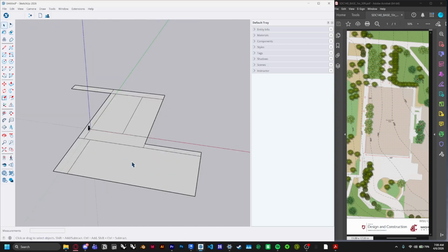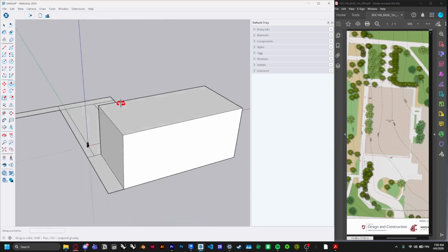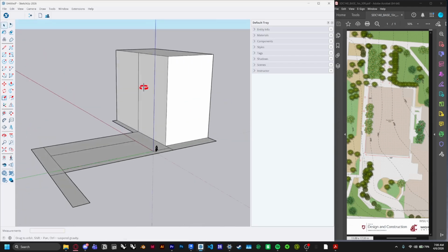Now that you have the Carpenter Hall box layout, go ahead and click the extrude tool that's right adjacent to the move tool, or one diagonal to the rotate, and click on the surface that you want to push and pull once. So click it, and then you can move your mouse around, and once again the numbers will change in the distance box. And go ahead and set this to 80 feet for the rough height of Carpenter. It's not exact, but it'll do for now.